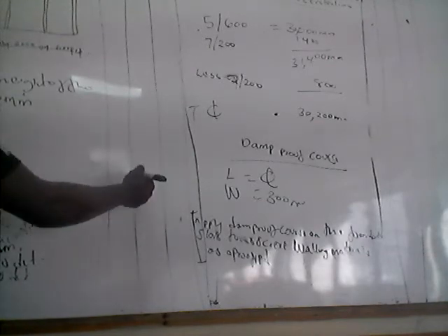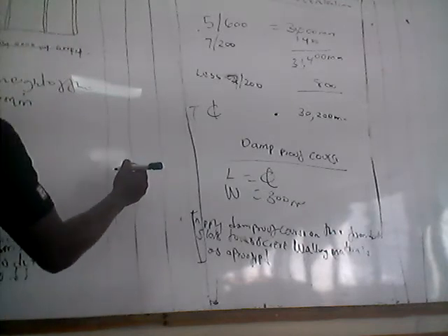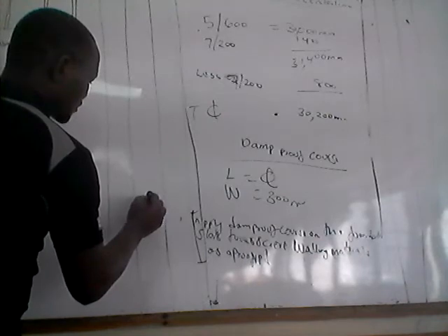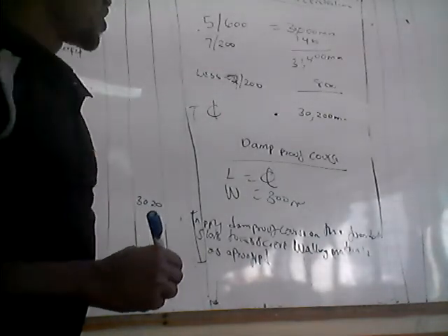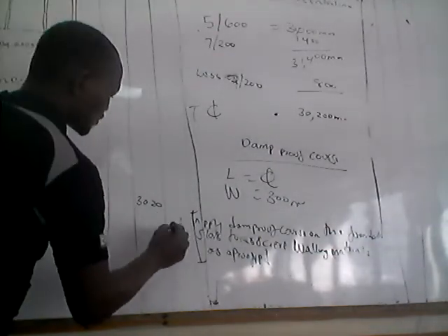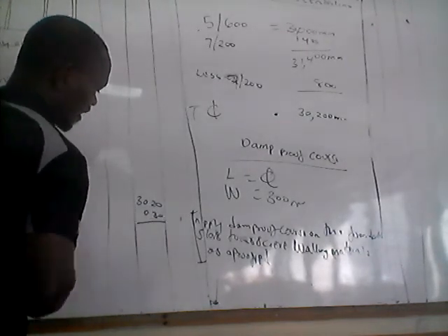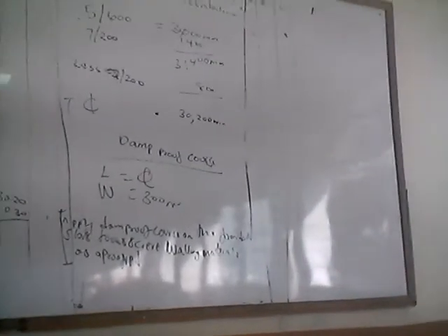That's our description. On the entry column, this is where you have to put the dimensions of this dampproof course. Then you say the length becomes 30.20, because we always insert figures in meters. Then it becomes 0.3 meters. Then you close your entry, and that entry is done.